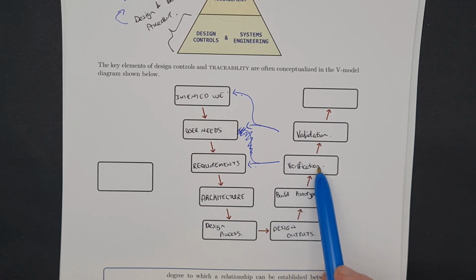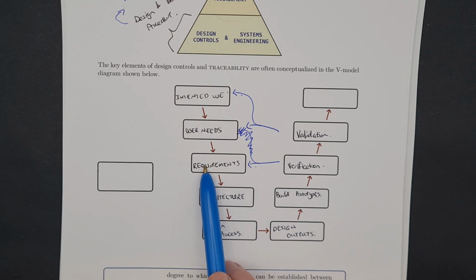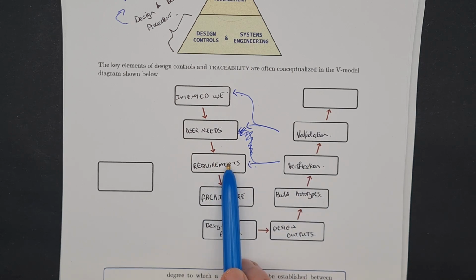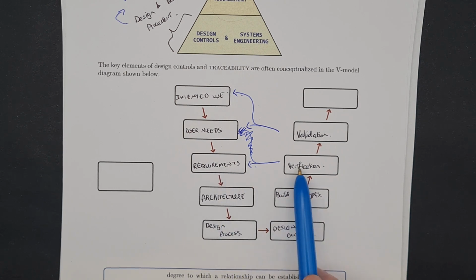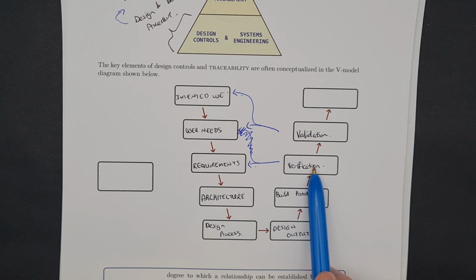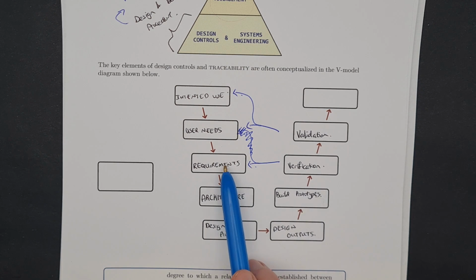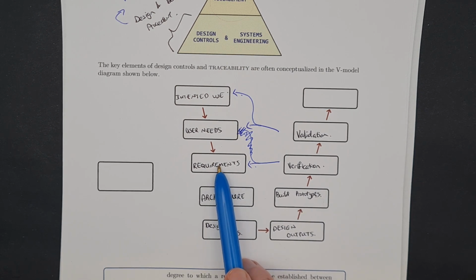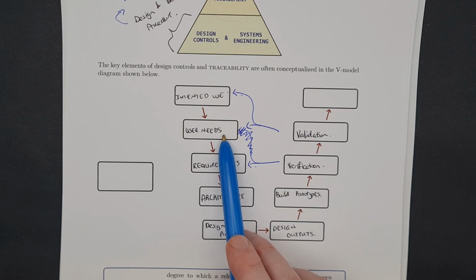Here, say, it could be something like a requirement for a pulse generator that it shall output 200 volts plus or minus 20 volts, and then we'll test the AED with an oscilloscope and whatnot to verify it actually produces the correct pulse that was defined in the requirements. But that requirement doesn't actually provide evidence that the defibrillator can actually be used to defibrillate a person's heart.